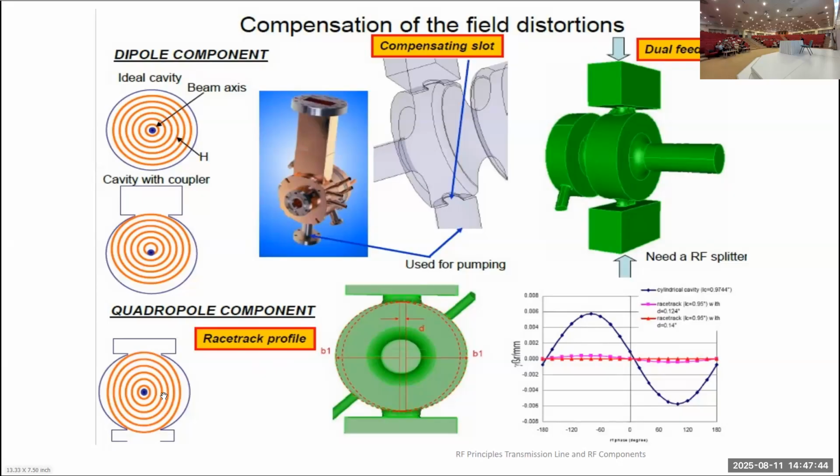But here, when you are coupling from both sides, always the TM010 mode is excited in the cavity. But the problem can be the phase difference. Generally the path length can be increased or decreased or can be different, and that path length can cause the problem. You have to count the phase length.